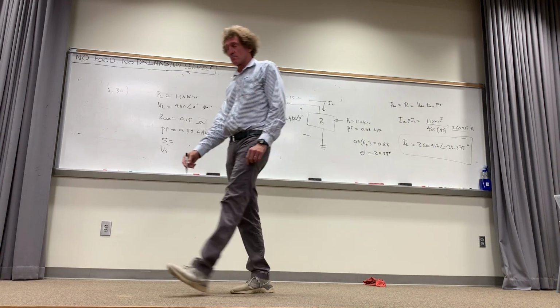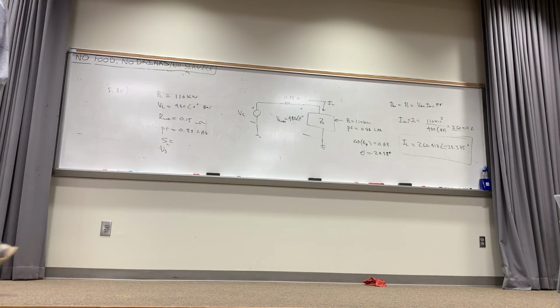Yes? So when you get that angle, that's theta V minus theta I, but theta V is 0, so I don't even need to put it in. When theta V is greater than theta I, it's leading, and vice versa. When the voltage is ahead of the current, yes. In other words, if it says leading, then the current would have a positive angle of 28 degrees. Okay, I got some wires crossed, I appreciate it.